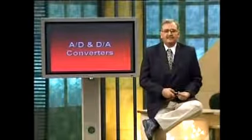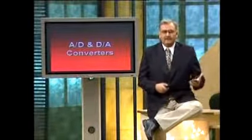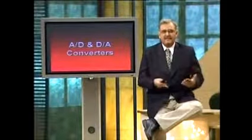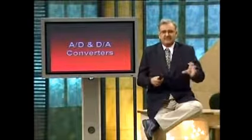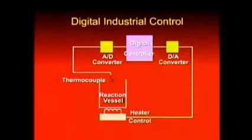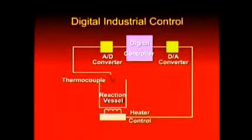Let us have a look at the diagram and see how the analog values are going to be converted into digital values, processed by a digital controller, and then the digital controller generated digital values are going to be converted back into the analog form. The diagram shows a reaction vessel inside which the chemical reaction is taking place. The vessel is being heated by some form of a heater. A thermocouple, basically a device which converts temperature into corresponding analog voltage values. An A to D converter, which converts the analog voltage representing the temperature of the vessel to the digital format.